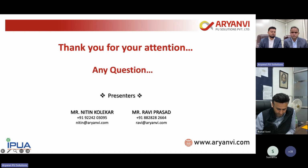With that, you can make sure that it will not get damaged. We recommend maintenance of the heat exchangers every 2 to 3 years, and after 5 years we recommend changing the tanks if you don't want to risk your machine. Thank you, Mr. Ravi. I think that helps.